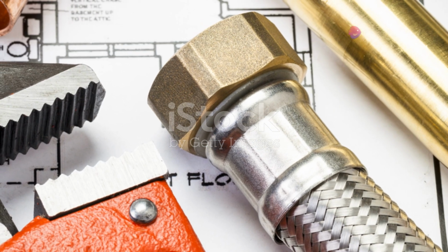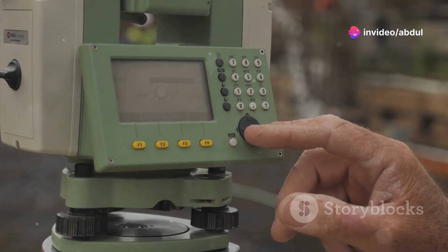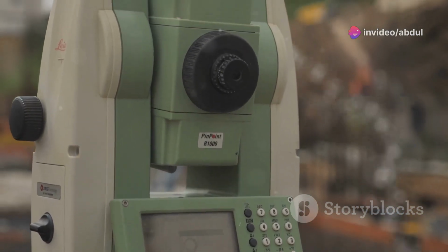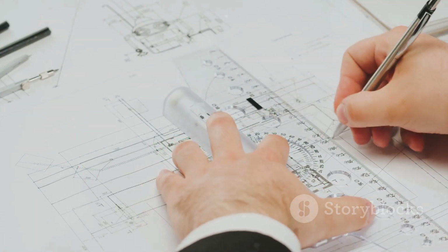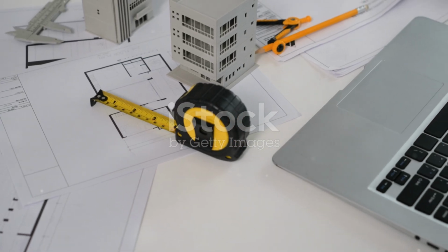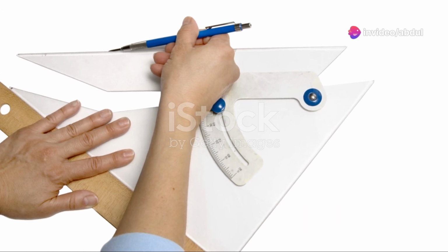It's important to use a consistent dimensioning style throughout your drawing. Specify the units, precision, text height, and arrowhead style. You can save these settings as a dimension style for future use. A clean and consistent dimensioning style makes your drawings look professional and easy to understand.